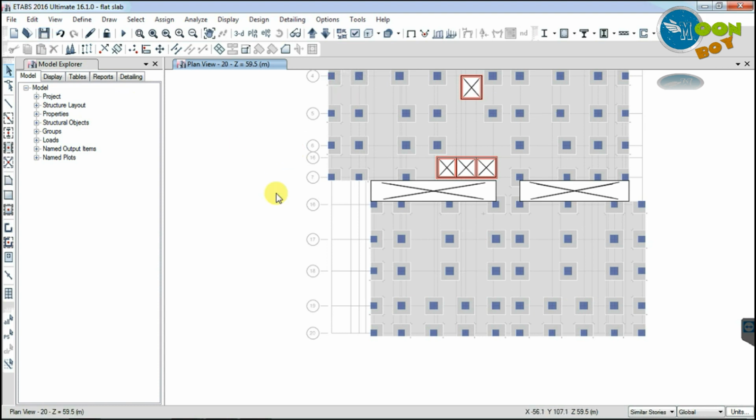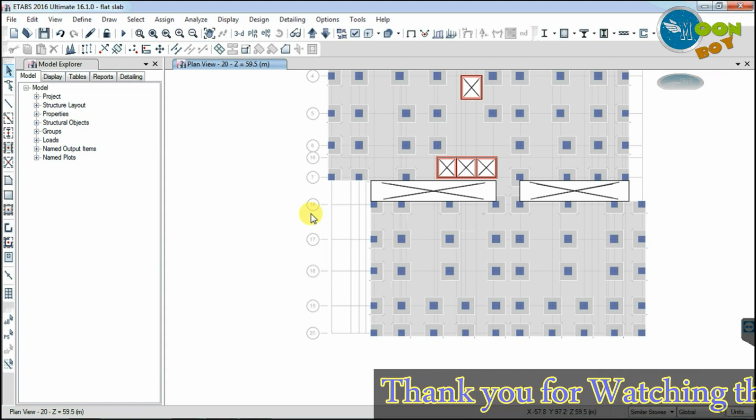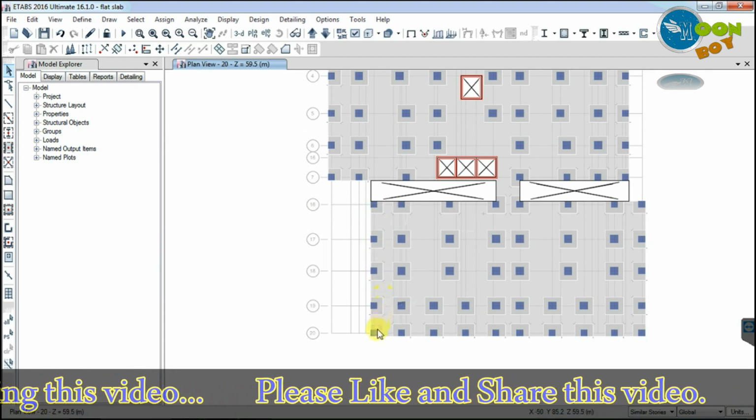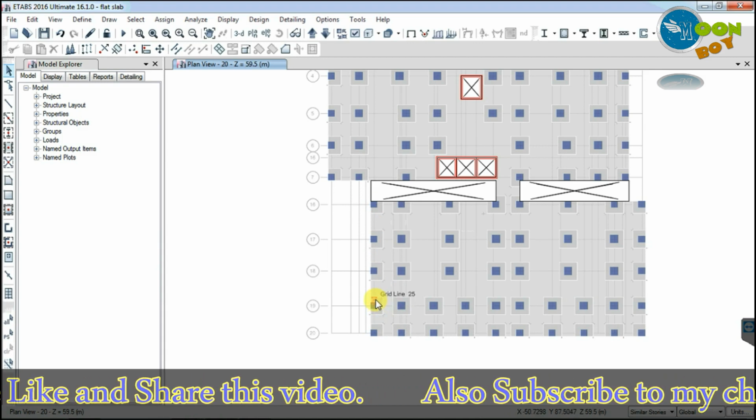For this, we have to give outside shear wall, sir, for peripherals. But there should be some openings also, no? Yes, sir. In the outer walls. Is it total concrete shear wall? Yes, sir. Okay. Then we have to provide at the grid line only, from column to column. Yes, sir. Column center to column center.